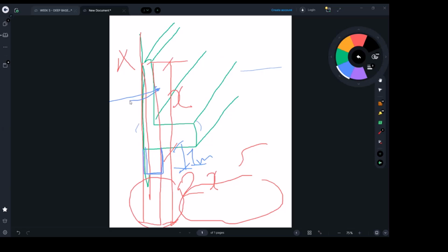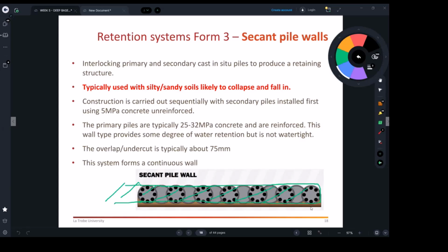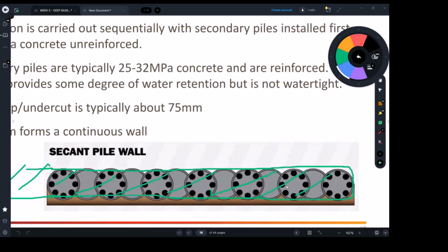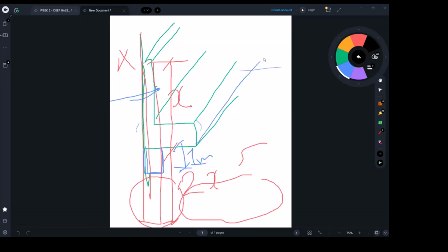So what I was asking you earlier is just while we are talking, because when someone looks at this, they say we are always putting the piles next to each other. Why did we not just use a normal retaining wall that we know about from undergraduate or have seen? The reason is this: we cannot batter, we call it battering the soil, sloping the soil.